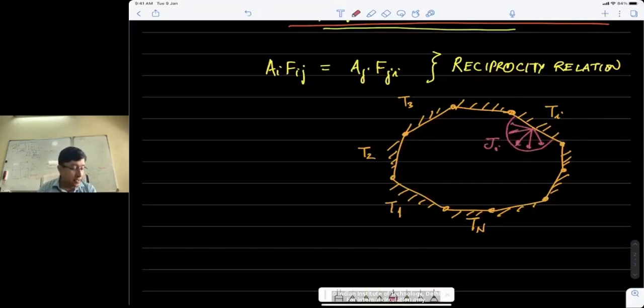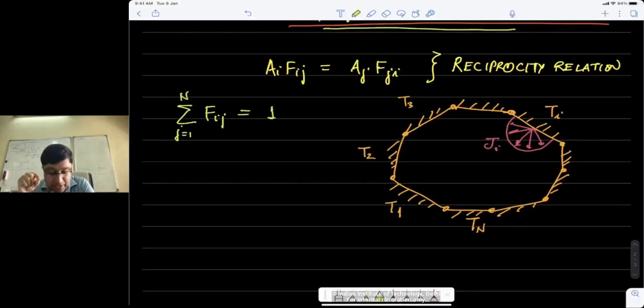Now, what I'm saying is that the view factor has a very powerful way of using this. You need to understand that if I look at view factor Fij and sum it over all j going from 1 to n in this n surface enclosure problem, then this sum should be equal to 1. That is just conservation of energy, if you want to say it. Because what it's saying is that radiation leaving surface i in an enclosure must be intercepted by someone. It cannot just disappear. That is basically accounting of all radiation. So all radiation leaving i reaches some surface j.